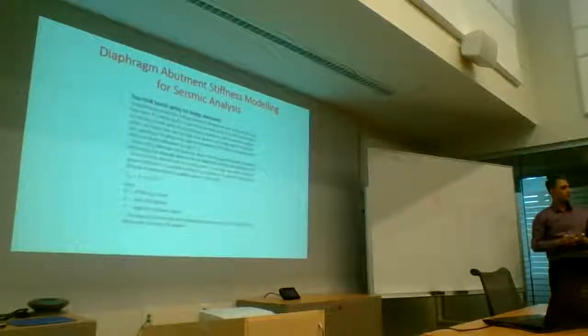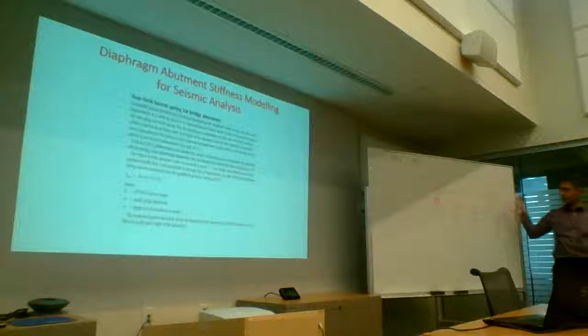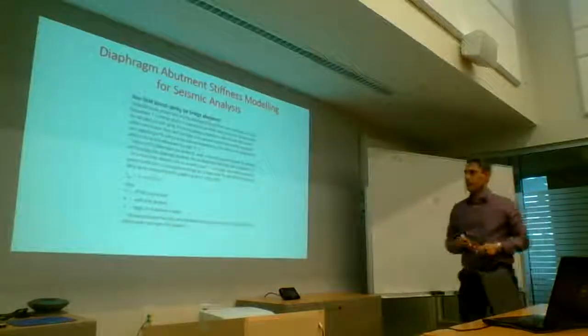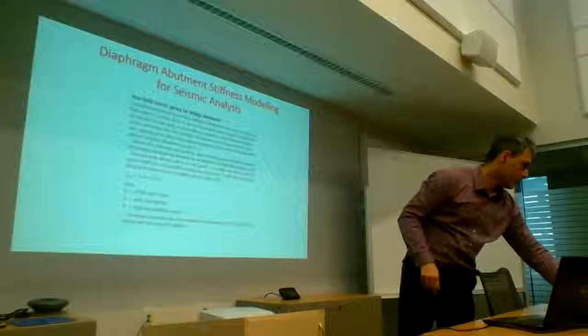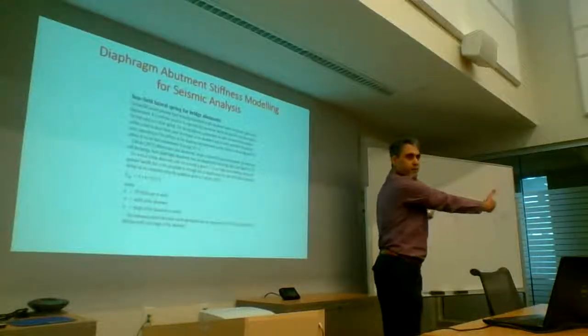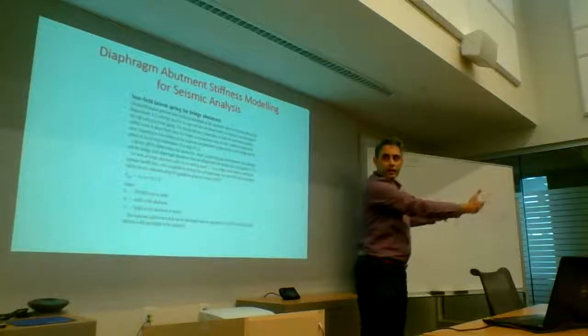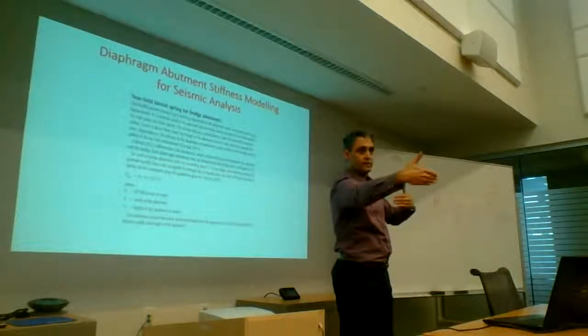Right? So now there is a lot of stiffness. What is that going to do? Attract a lot of force. But they've pulled the load out of these. Okay? So that's the whole idea. And usually they're several times stiffer and stronger. This is an extreme case I'm talking about, but reality can get quite close to this when you're looking at short to medium span bridges with wide decks.